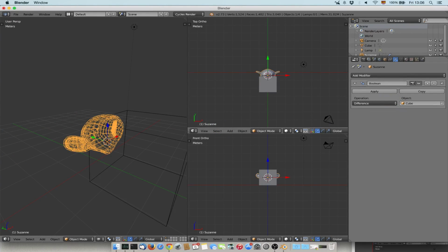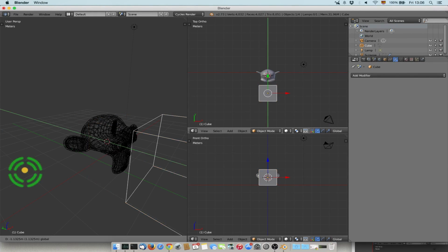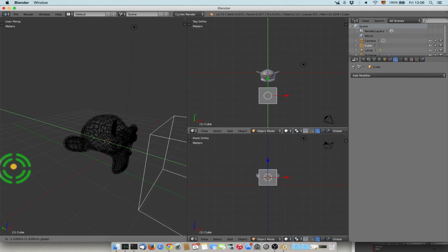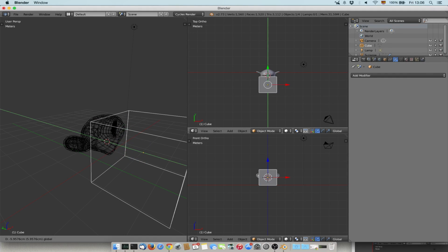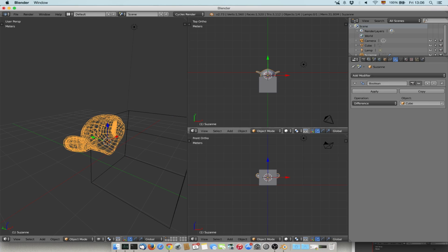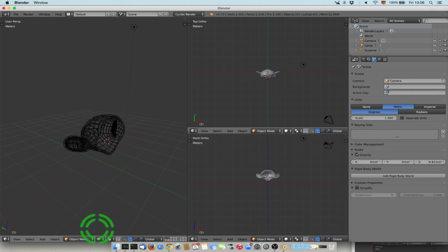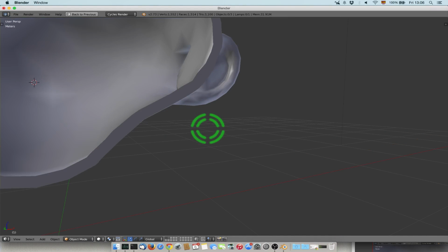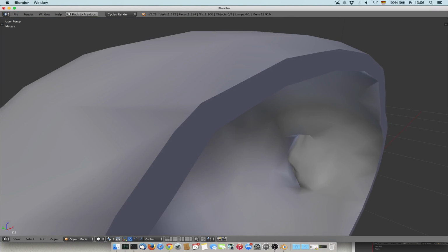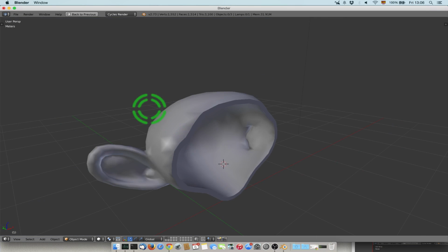Yeah, and this is still dynamic. So if I move this, it's not permanent. Okay, you can change it. If you want it to be permanent, you click on apply, and now it's permanent. For example, let me delete this. This is what we get. Okay, so you see, it makes a shell. So now you can put your Arduino inside. Okay.